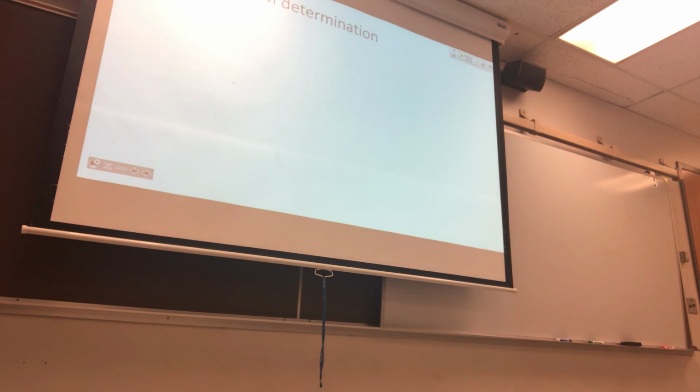So let's go ahead and write those equations down and make it a little bit more clear from what the video had. So our Q, that's our CFMs. That's equal to the volume of your tank times the pressure reading. The pressure gauge reading you get for the second part minus the pressure gauge reading you get at the start.